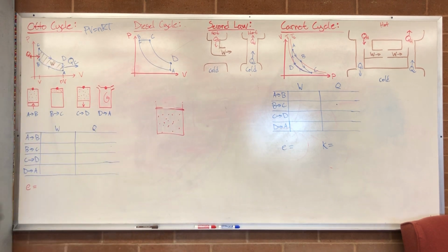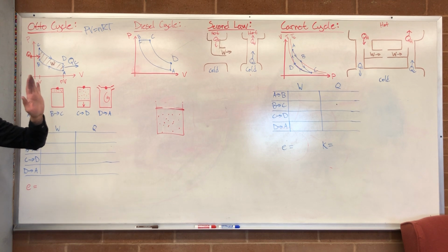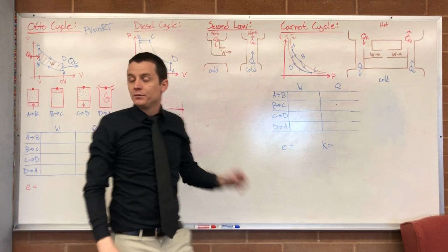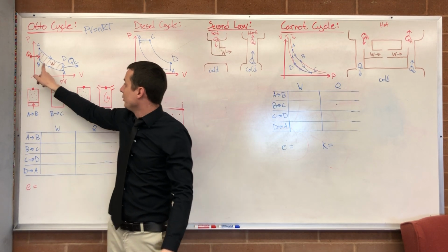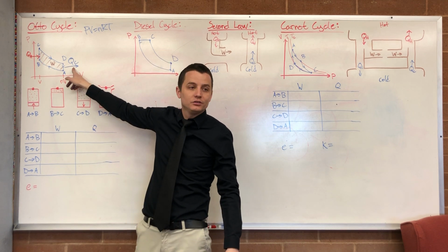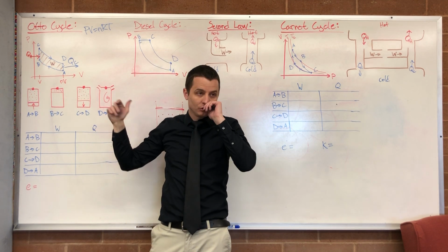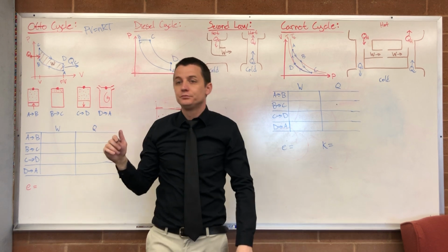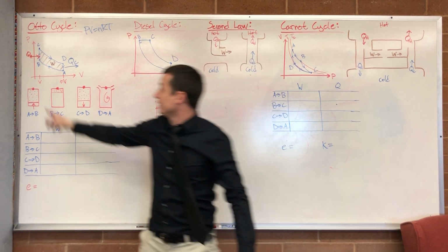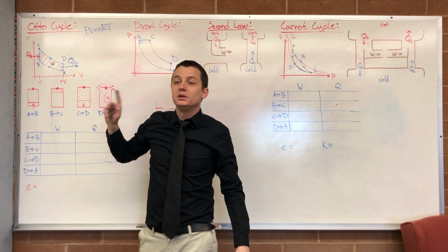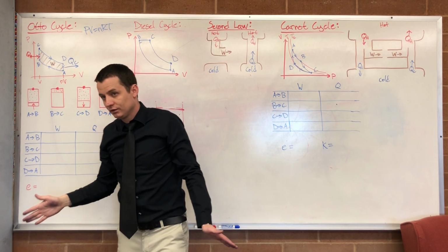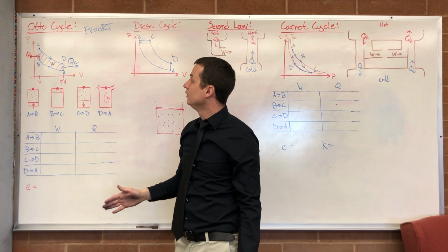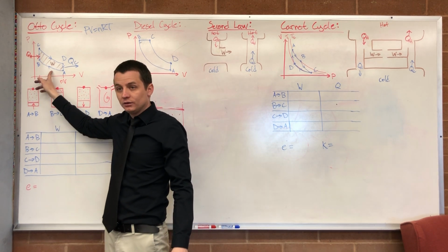So looking back at this little diagram, here's high level how all heat engines work. Here's a particular heat engine. Okay. So heat is added to the system. Some of that heat's converted to work. Some of that heat escapes to the cold source. Do they escape at the same rate? More heat is added than escapes, because some of the heat had to be converted to work. And that has to stay in a cycle, because the gas also does work.